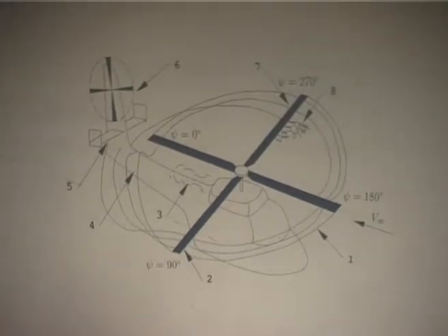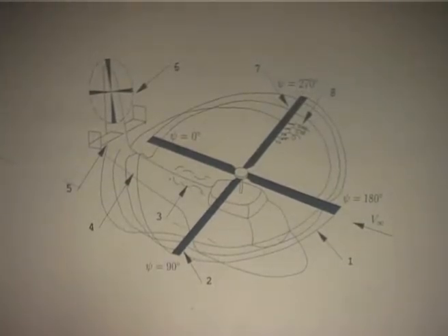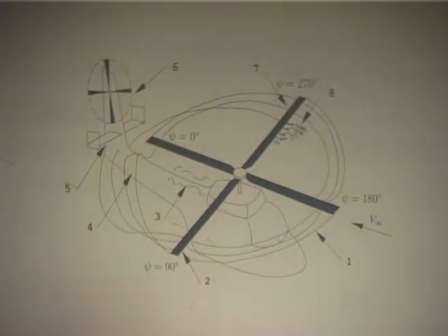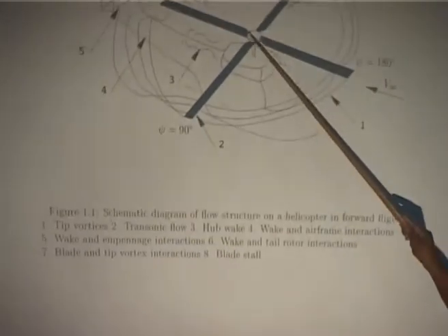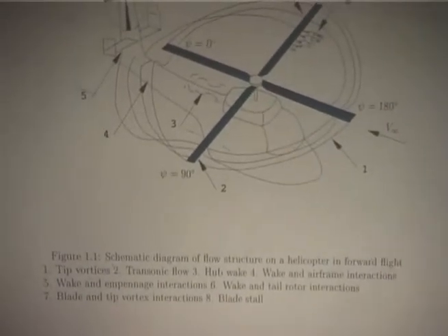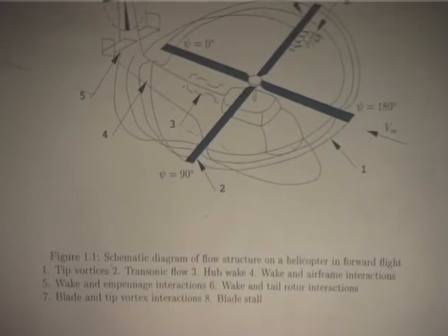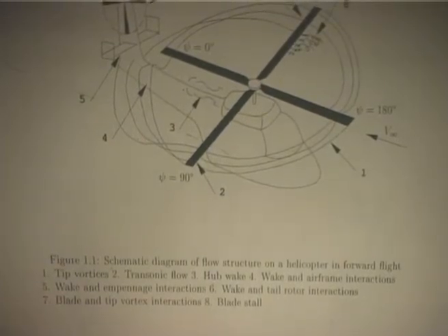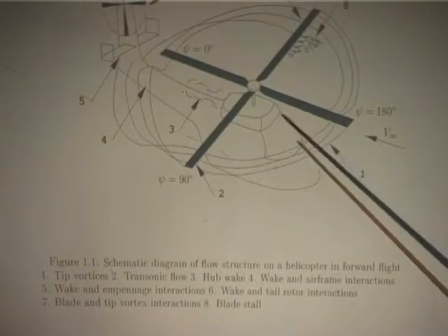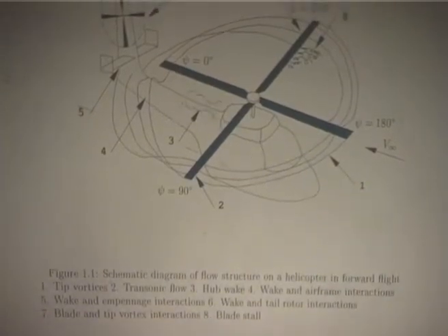In the sense, they will all interact. This is what they call blade vortex interaction. And then at the tip you will have a transonic flow, then the hub is there, and then the engine deck, and in forward flight that will start giving its own disturbance to the flow, and this flow will all go and hit the tail, okay.